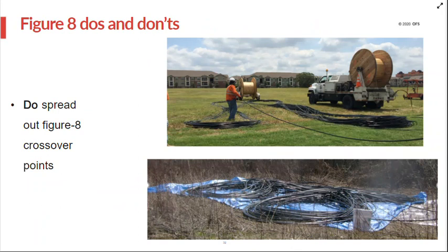Figure eights. Figure eights generally are pretty benign. Just a couple of words on figure eights. We do recommend that you spread out the crossover points of the figure eight. Also, if you're figure eighting a long length of cable, figure eight the cable in 2 piles or 3 piles. Don't make one huge pile. Spread the cable out.